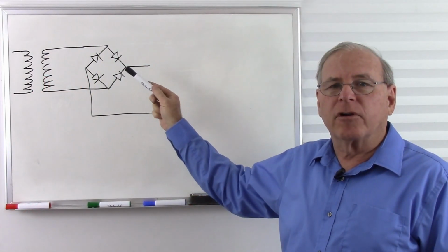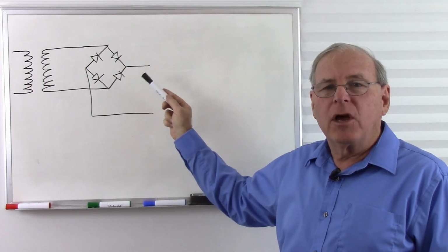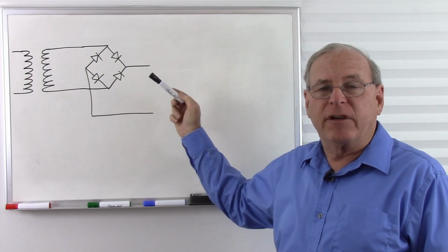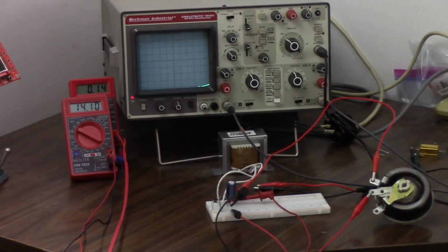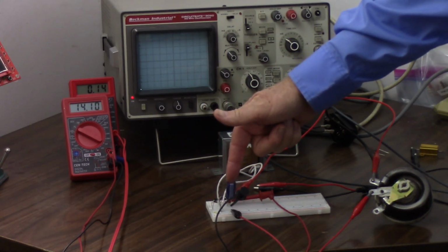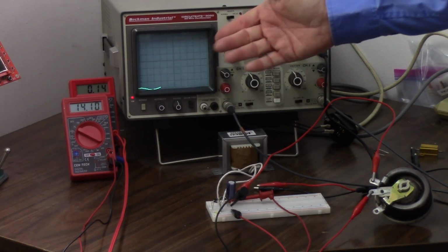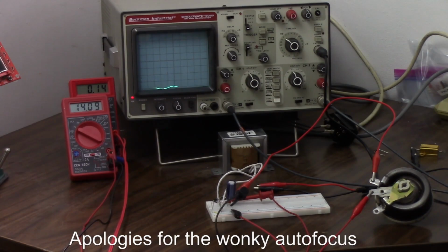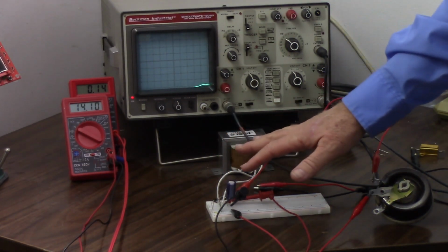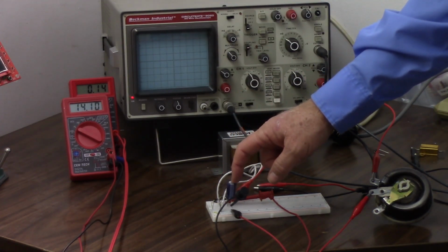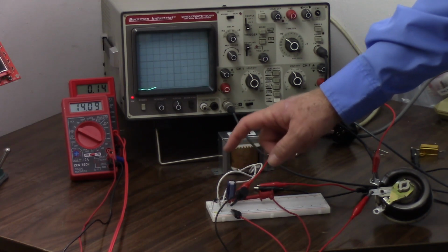So the next part of the circuit to look at is our bridge rectifier. We expect to lose about 1.5 volts across that. Let's test it and see if that is correct. Okay, now since I'm measuring DC voltages, I'm coming off the rectifier and I put the filter in there. Since I'm measuring DC voltages, I can go ahead and use my meters and not have to use the oscilloscope. And the question is, how much current can I get out of the whole system before the voltage at the capacitor drops below 12.5 volts?